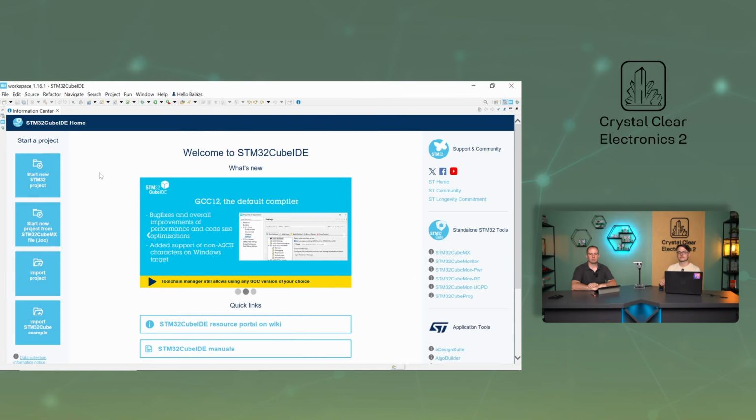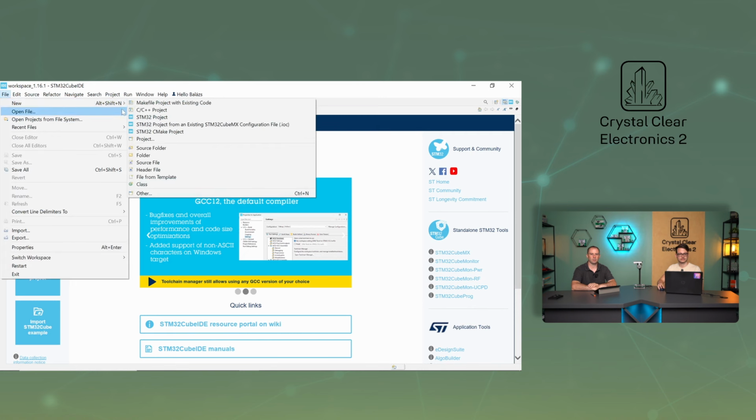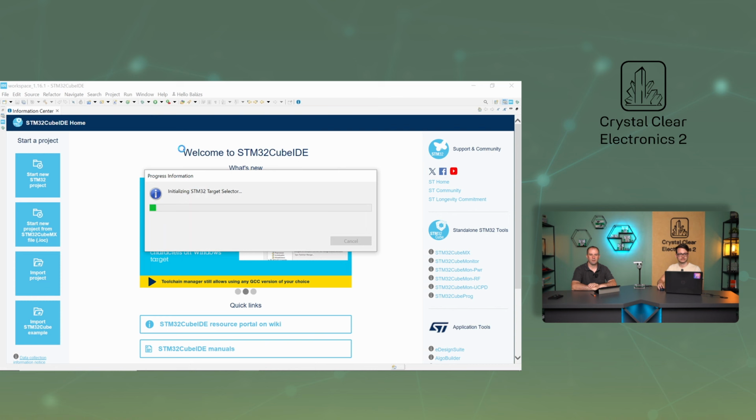In the first example, we will flash an LED by the counter and timer module every second. In the following, we will explain step by step the functionality of the program to be written and the necessary settings. As a first step, let's create a new project in the STM32Cube IDE development environment for the microcontroller on our board. This can be done by clicking on New STM32 Project in the File menu.